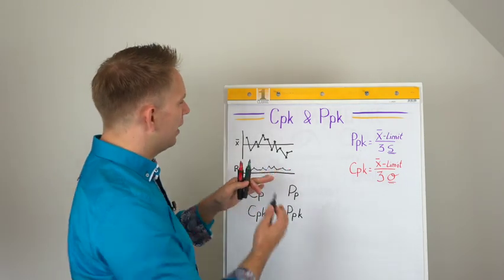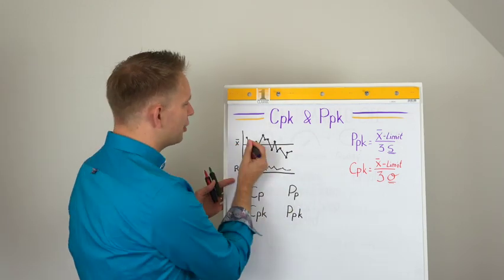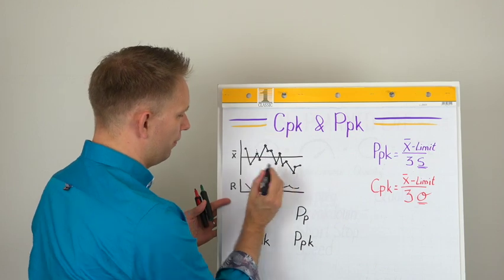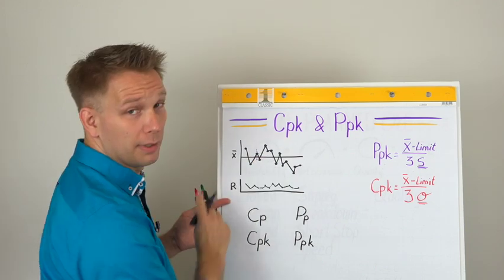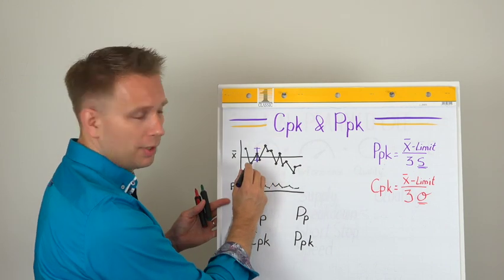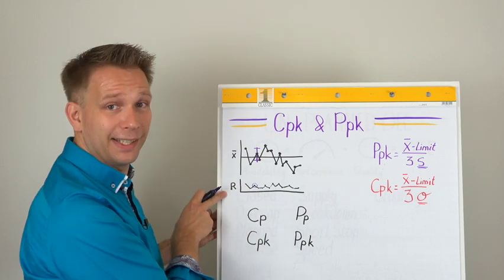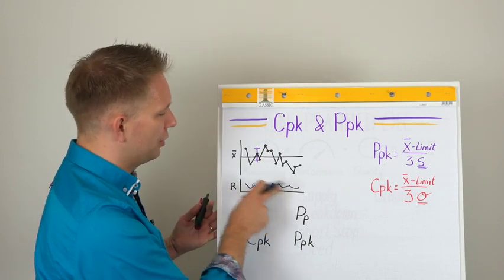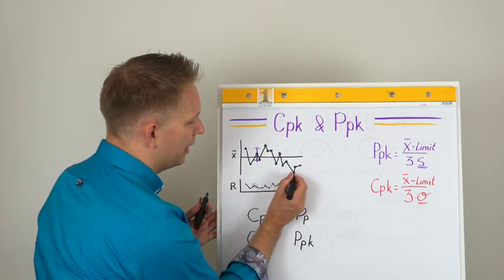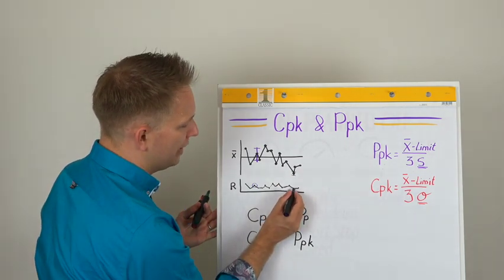You see, when we take a sampling plan where each of our samples is actually a number of individual points, we get a range and a sample here. And this range is reflected in the chart under here. You see there is also a couple of points that have almost no spread. So we have a very small range.